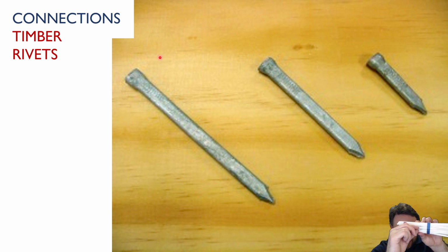But that does mean that if I'm installing timber rivets, which have a cross-section that's kind of flat, I have to install them so that the long part of the cross-section is in the direction of the fibers. If I install it like this, that really defeats the purpose, because now I have to cut through all of those fibers basically in order to fit this in. Okay, so I need to install it so that the flat part is in the same direction as the fibers of the piece of wood. Okay, but then this is a really good way to connect a steel plate to a piece of wood.